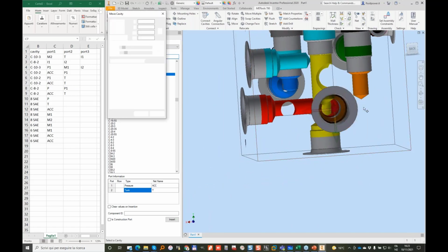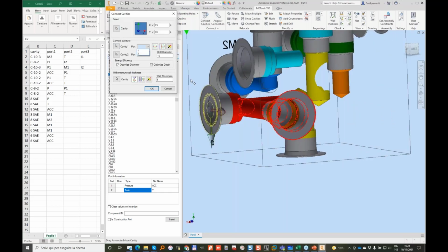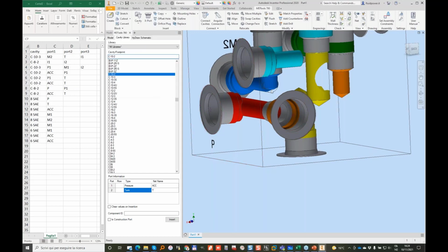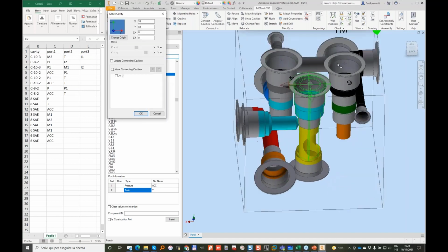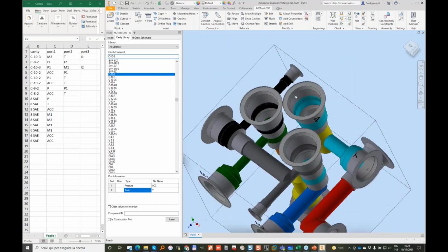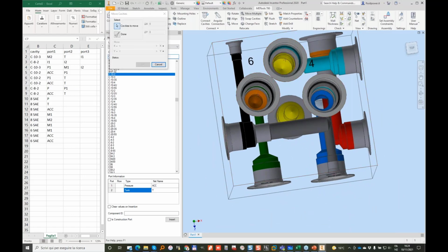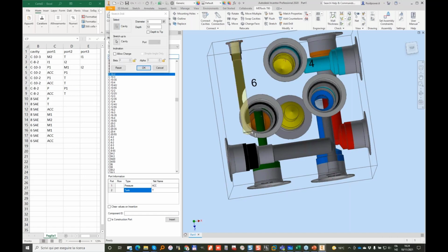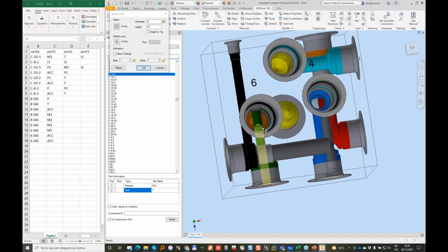So this valve now can be moved to the left. So in order to reduce the drill, I can connect directly these 2 ports. So in this way, I have room here. The yellow is now okay in this position. Let me move it slightly. These 3 are solenoid valves, so they will have some interference with the coil, and we'll see later in the assembly. So I will use move multiple again to move these 2 valves down on the Z direction. And now I will stretch my drill to make the connection. And I also can reduce this drill.